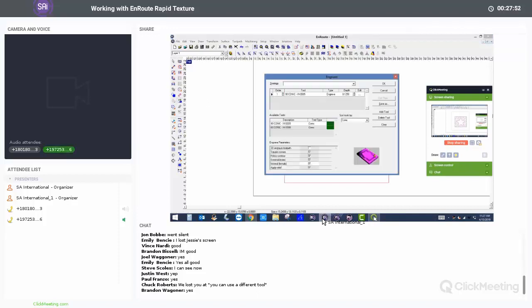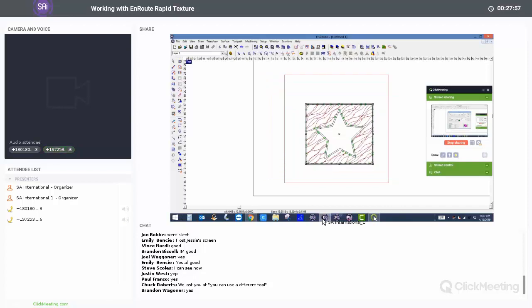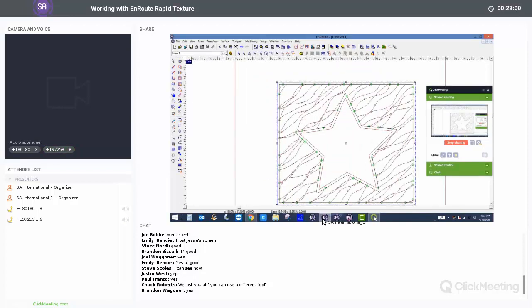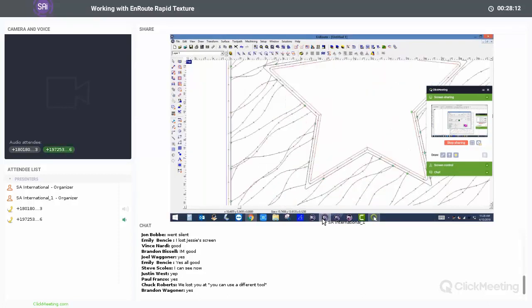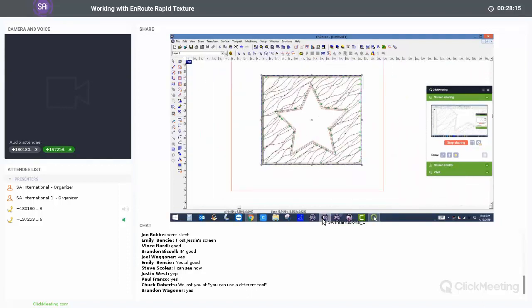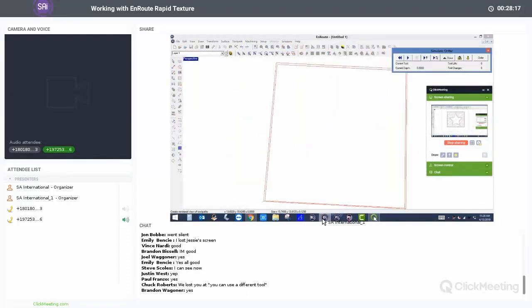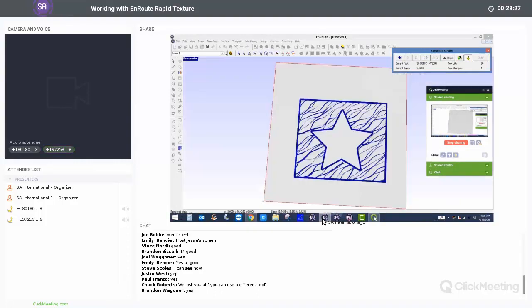Now I'm going to engrave. I'm going to use that conic tool. Make sure follow contours is checked on. And then inside here, I'm going to create a 3D engraved toolpath. It is going to be a 1/8" depth, because remember that was our offset. And what it does is it will come back in and it will actually clean up around this area. So now when we render, you should get a nice clean texture along with a 2.5D star.